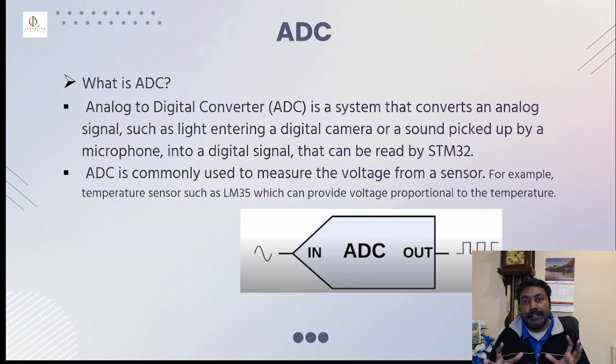Most of the sensors that we face in real-time systems will have some sort of analog signal, and you need to use a converter to connect to the microcontroller, so the microcontroller can understand what you're interfacing with and it gives you a digital value, because all microcontrollers are digital processors, so it doesn't understand the analog value. So that's why you need a converter to convert from an analog signal and give a digital signal as an output.